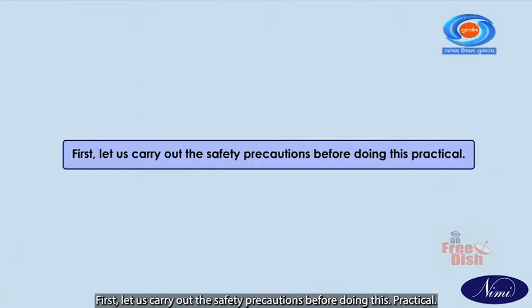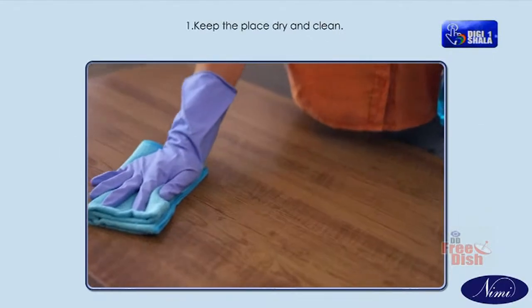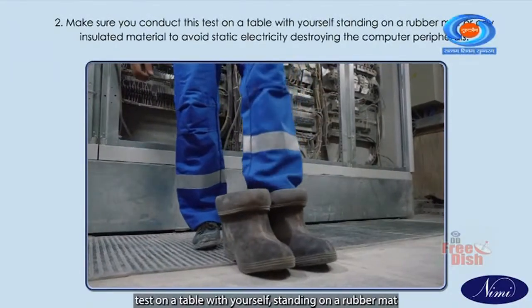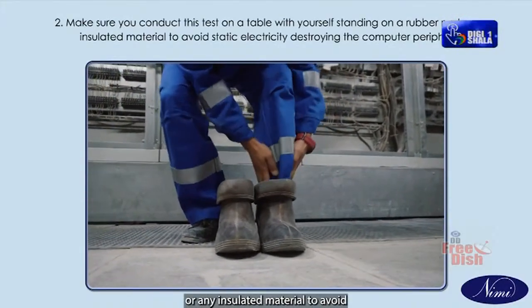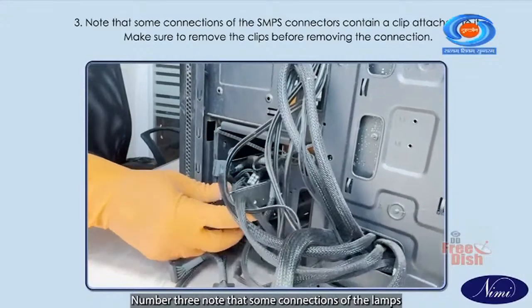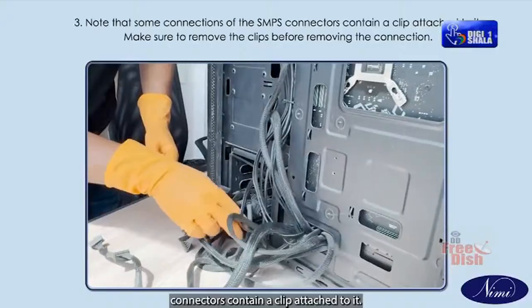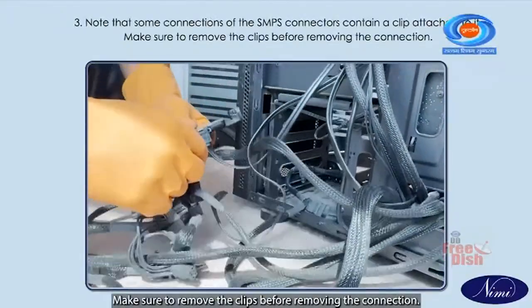First, let us carry out the safety precautions before doing this practical. Number 1. Keep the place dry and clean. Number 2. Make sure you conduct this test on a table with yourself standing on a rubber mat or any insulated material to avoid static electricity destroying the computer peripherals. Number 3. Note that some connections of the SMPS connectors contain a clip attached to them. Make sure to remove the clips before removing the connection.